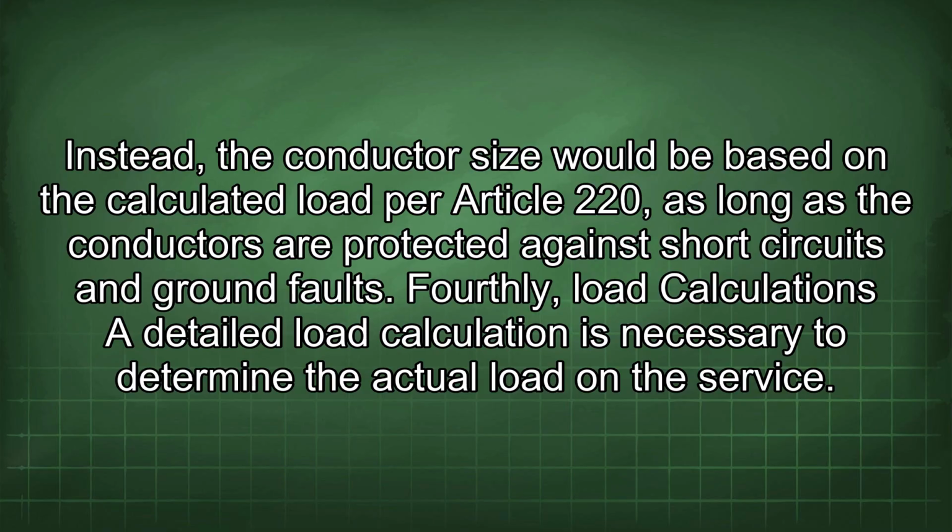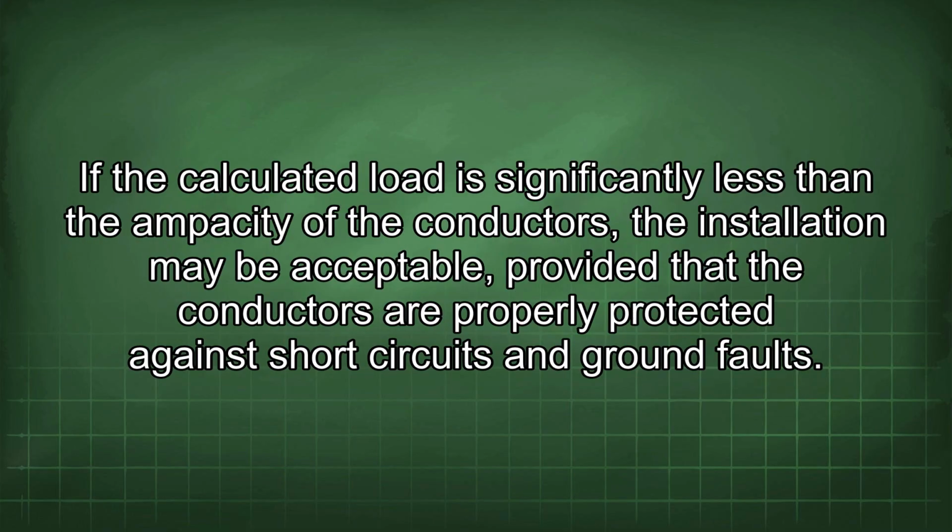Fourthly, load calculations. A detailed load calculation is necessary to determine the actual load in the service. If the calculated load is significantly less than the ampacity of the conductors, the installation may be acceptable, provided that the conductors are properly protected against short circuits and ground faults.